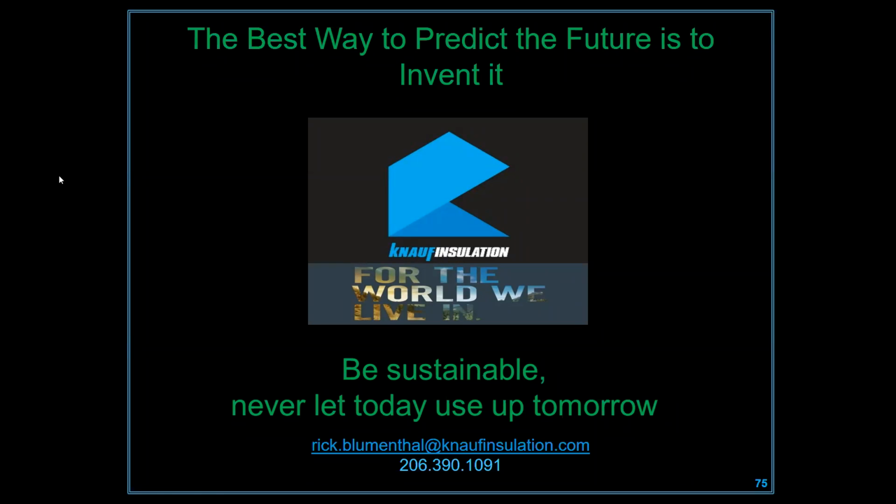Sure. So let's just start with the brick, because the simple solution in brick is to create a drain plane behind the brick. Bricks are sponges. They're very hydrophilic. They soak up and hold on to a lot of moisture. So when that moisture gets released, it gets released in 2 directions, again, depending on the conditions. So that gap behind there was originally measured by the mason's thickness of his fingers when he put his brick down.